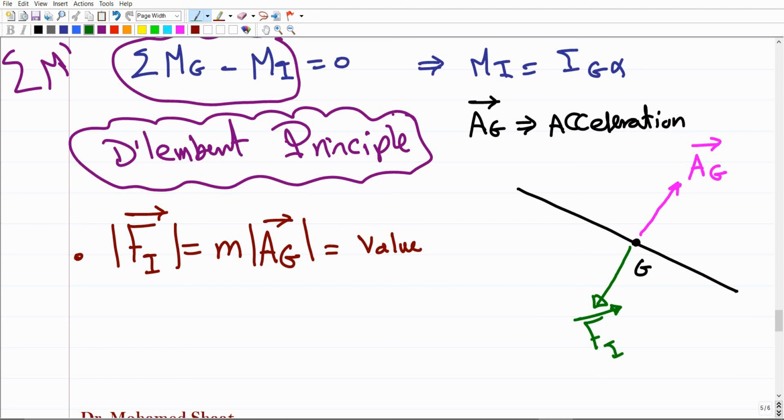And we deal with this force, already acting at this point G, like it is an external force. So if we have another force at this end and one force at this end, this is a three-force member. Make sense? But plus this force, how about if this link is already rotating? Somehow this link rotates in this direction, with alpha.